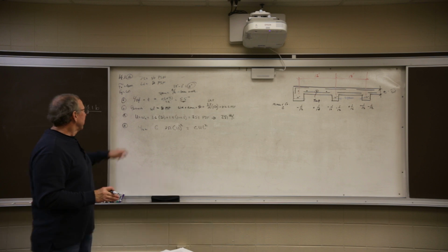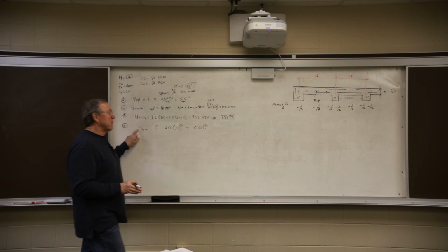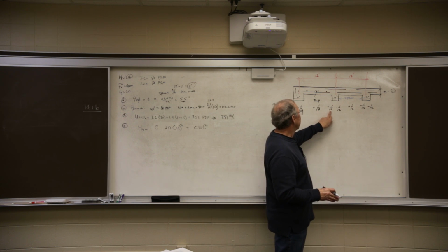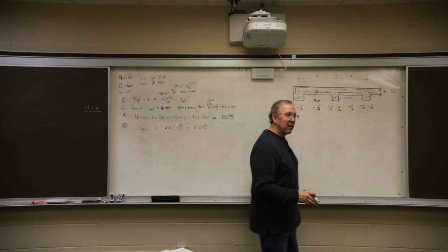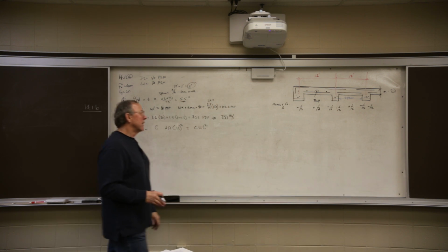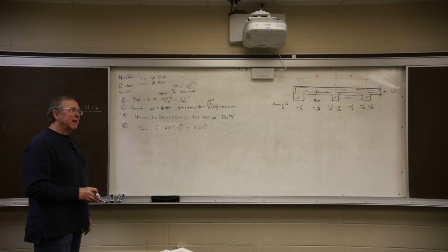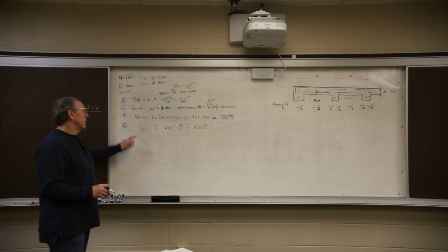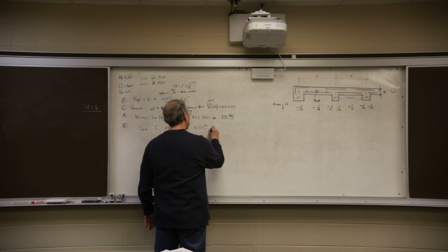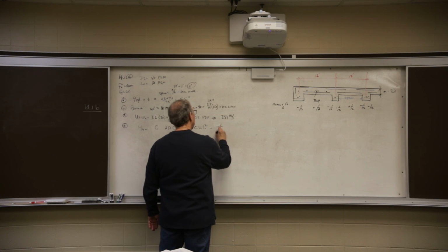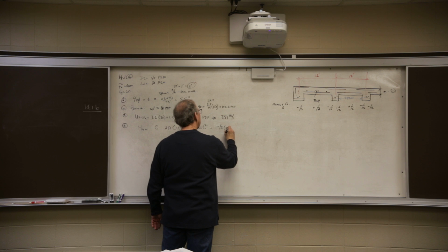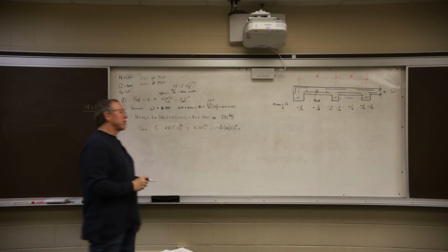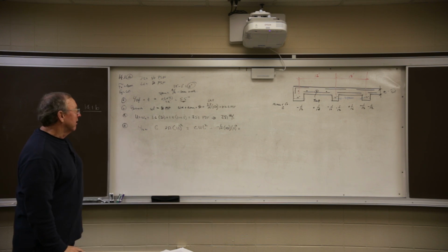So what number gives me the biggest moment if I multiply by 1/12, 1/14, 1/10, or 1/16? Hopefully you see that if I multiply by 1/10, I get the worst case, or the biggest moment. So there's the worst moment in that particular slab.